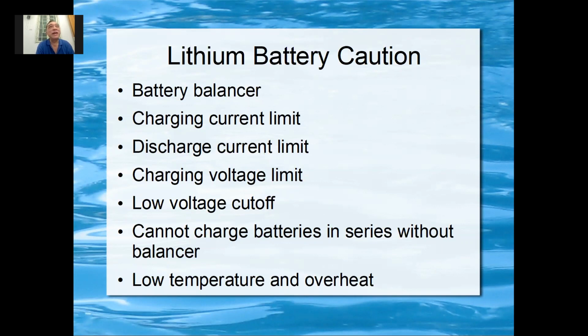That's why people even die when the battery overheats. When you charge the battery under the pillow, or you charge it and then you fall asleep and the battery is covered by your pillow or by your body, then it overheats and you can get a problem. Some people will charge the battery in the pocket and the power bank is in another pocket. So the power bank charges the battery and the battery will overheat because in your pocket you have very little ventilation, all closed up, your body, your pants and all this. So the heat cannot dissipate fast enough and then it overheats.